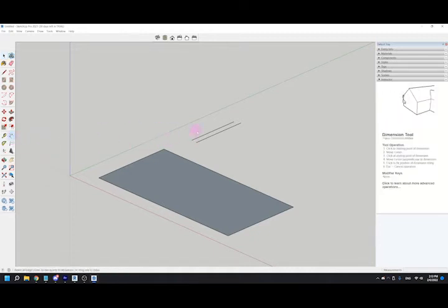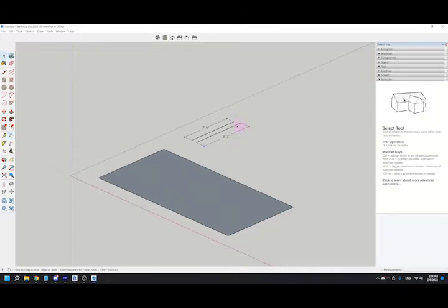And I can even put a quick dimension that's 7'9" versus 8'3". This is a tool we're going to go over in the next lecture, so don't worry about that too much. I just wanted to prove to you that that's what that dash mark does. So it can be helpful in that you can use SketchUp to make some quick calculations for you without having to do any math, but you just want to be a little wary when you are typing your measurements in.